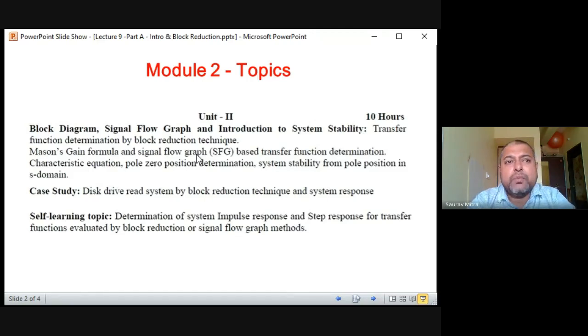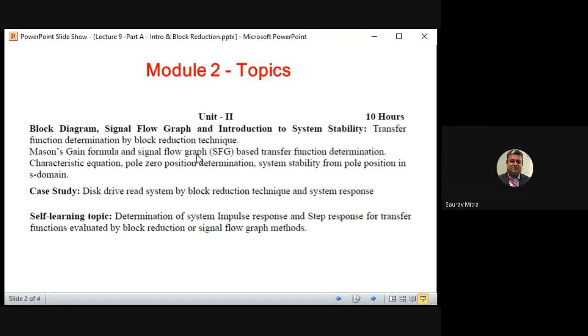Second thing, Y(s)/X(s) is given for different types of inputs. That is, X(s) can sometimes be a ramp, sometimes a unit step, sometimes an impulse, at certain times it can be sinusoidal as well. So X(s) is not mentioned in the transfer function. That depends on us. So Y(s)/X(s) is equal to a ratio of polynomials. Y(s) is equal to X(s) times the ratio of polynomials. Then if you take the inverse Laplace, y(t) is equal to the whole inverse. So you can find out the output in the time domain for any kind of input signal.